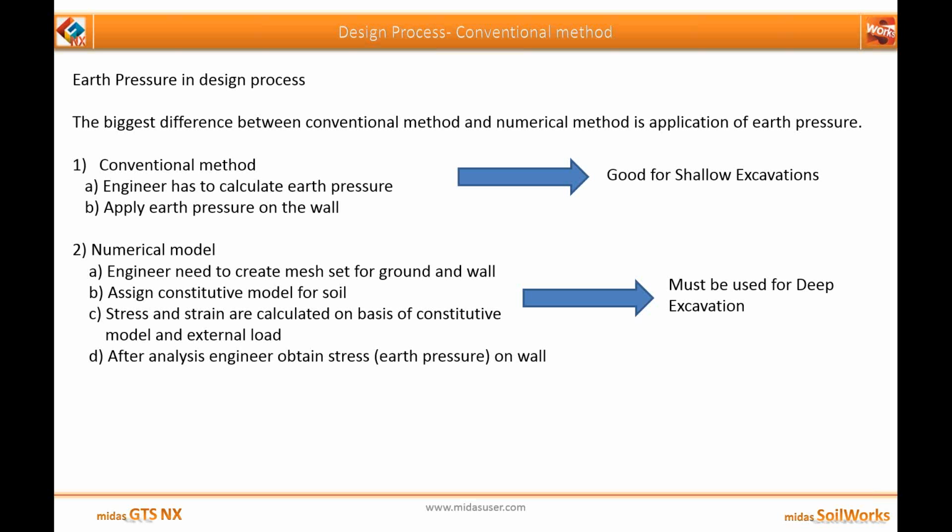So it is good for shallow foundations. But when we come to numerical modeling, the engineer needs to create a mesh for the ground and wall, and assign a constitutive model for the soil to model the behavior of the soil. Stress and strain are calculated on the basis of the constitutive model and external load. After the analysis, the engineer obtains the stress, that is the earth pressure on the wall. This kind of analysis is more suited for deep excavation as compared to shallow excavation, which is for the conventional method.